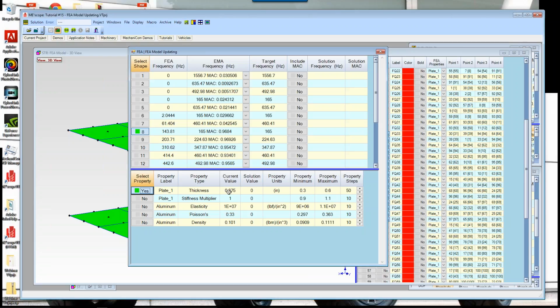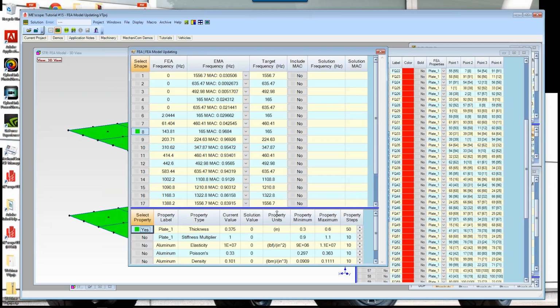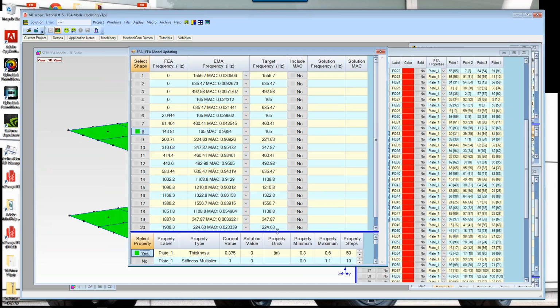We need to remove that element from the model and add in a new element that has a different thickness to it. So it works a little differently, and yet it uses the SDM algorithm, which runs very quickly, and will find the new modal frequencies and mode shapes for the finite element model. SDM uses mode shapes of the unmodified.